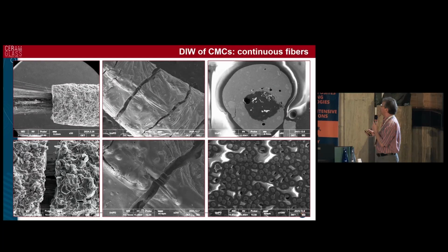And of course, we have a lot of things still to improve in terms of the shape of the filament, and also in terms of the presence of residual voids that come from the fact that we are using highly loaded slurries to reduce the shrinkage, and they are difficult to mix, even if we are using the correct mixing devices for this type of pastes.